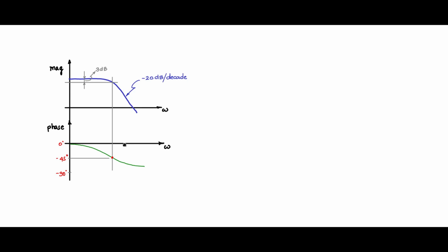So for us, the grid frequency is very stable. It varies between 49.5 to 50.5 hertz, which is a very small margin. It's more or less 50 hertz. So this line should be at a frequency which is 50 hertz. Then we can say now at this point the gain is 0.707 with respect to omega at DC, or the flat portion of this magnitude curve.